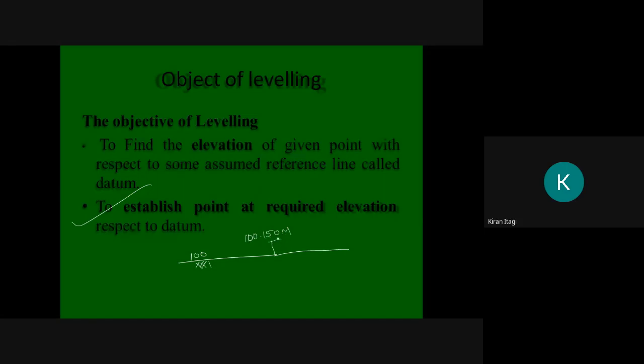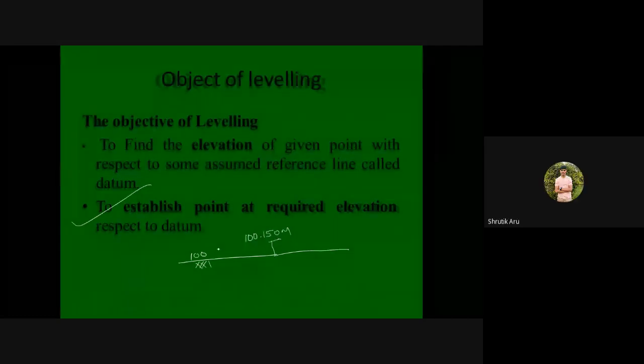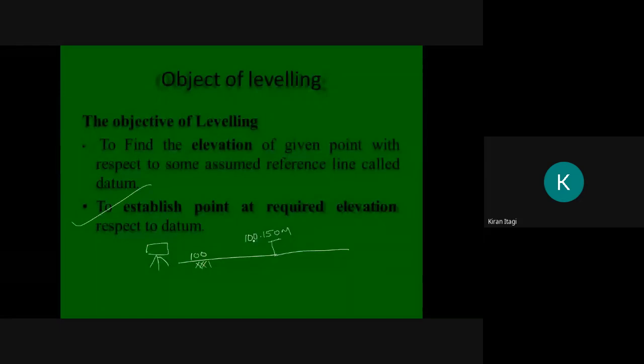So with the help of an auto level or dumpy level and this staff or scale, I will construct the step, and its level should be 100.150, that is 150 mm height.